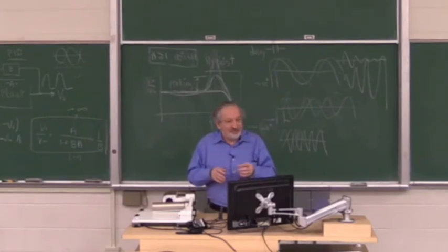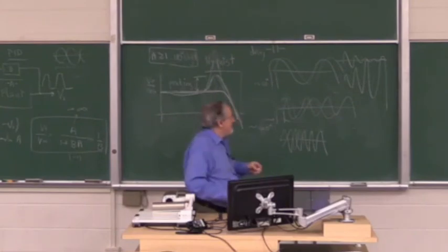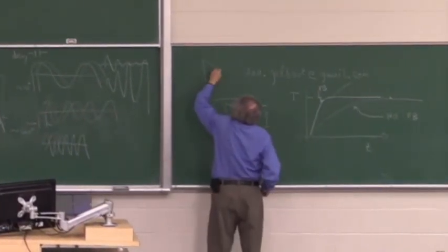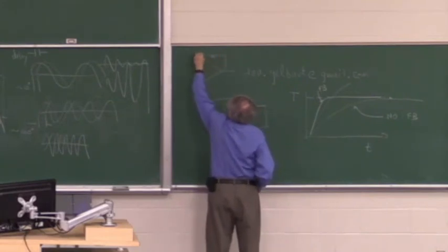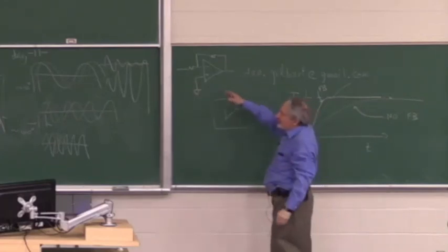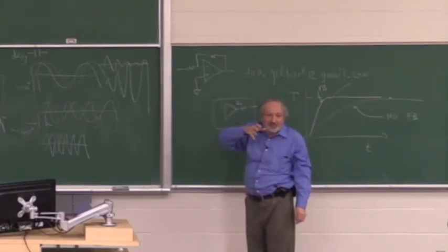And usually you have to design the system so that the gain will die before there is enough phase shift to be unstable. And that's what you do in op-amps when you sometimes add a capacitor. So when you design with an inverting op-amp, and you test it and you get this problem, it's a bit unstable.